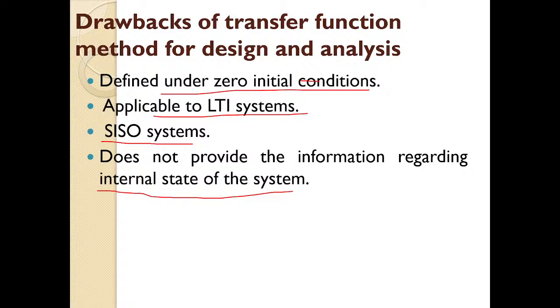So since the transfer function is defined only under zero initial conditions, is applicable only to linear time invariant and single input single output systems, and won't provide any information regarding the internal state of the system, we go for the modern approach of design and analysis of control systems, which is state space analysis.